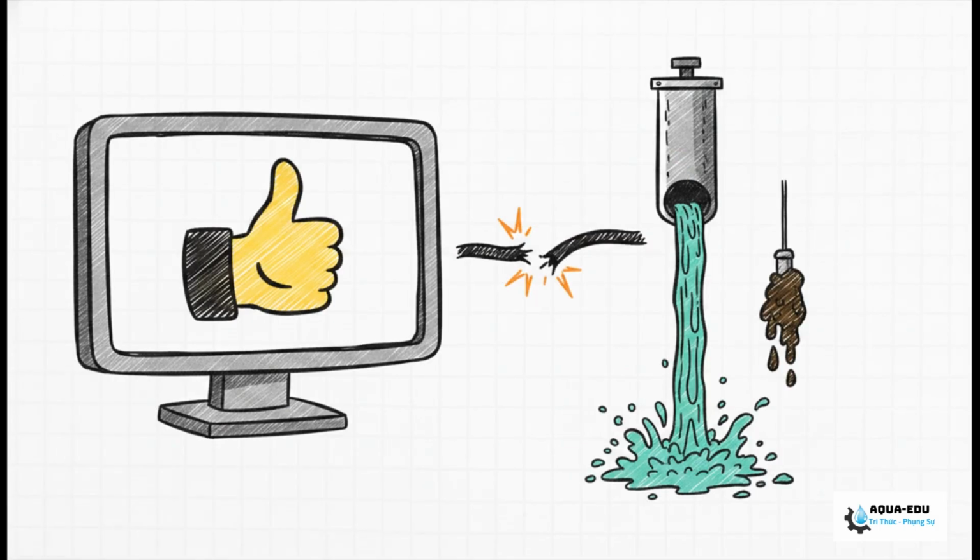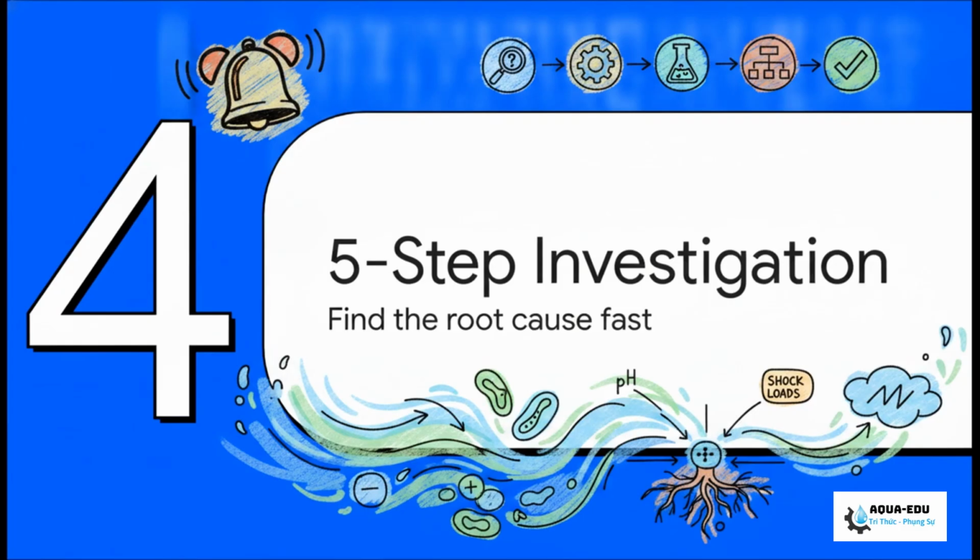And we've also got some massive blind spots when it comes to equipment failure. If your SCADA system drops its connection, or say your online pH sensors get fouled up and drift by more than 10%, your alarms are going to fail you entirely. You could be taking a massive acid hit, and your control screens will just sit there telling you everything is perfectly fine. Scary stuff.